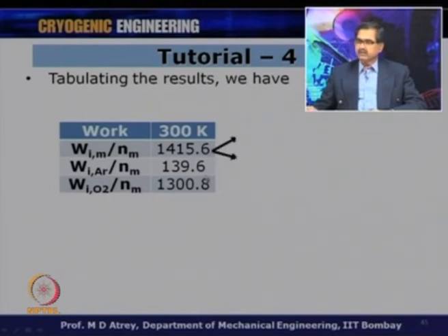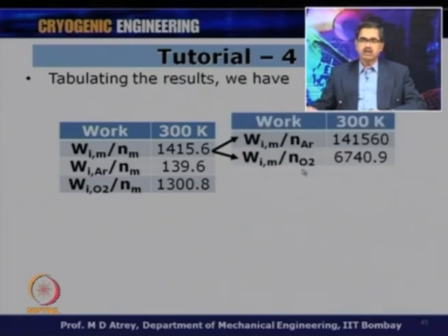Now, I can represent per mole of mixture as per mole of argon or per mole of oxygen. So, this is just a representation style. So, I can get now work of separation of mixture per mole of argon. So, divide this by the molar fraction of argon, which is this.